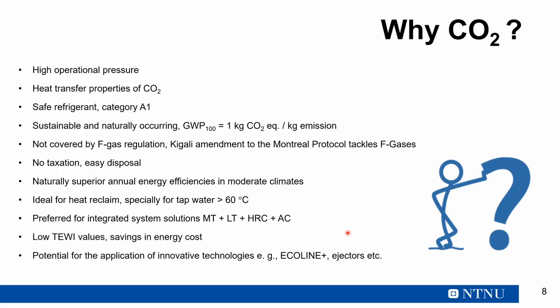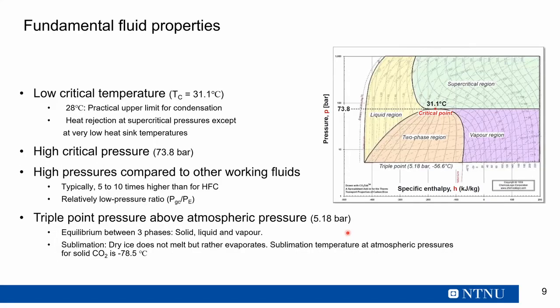While considering the fundamental properties, it is a bit different from the other traditional refrigerants which we normally discuss. The critical point is very low, and this is also an opportunity for this refrigerant, that it could work much more effectively in supercritical, or I would say transcritical, conditions. The operating pressure is definitely high, and as mentioned by Professor Ramgopal, if designed properly and used carefully, this could be one of the game changers we could have. And there are some other properties.